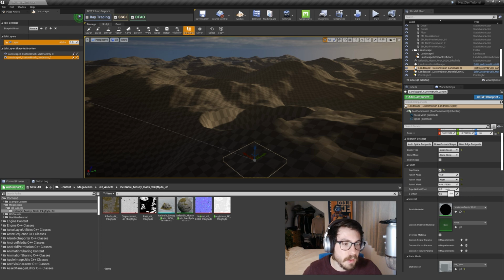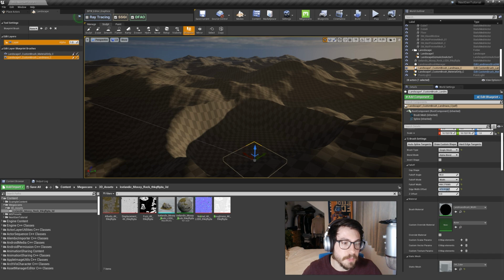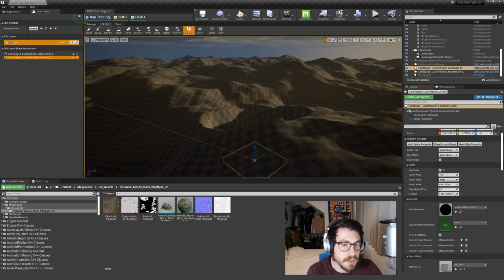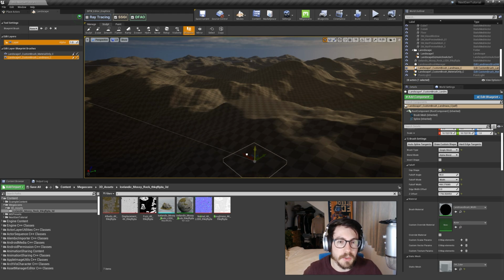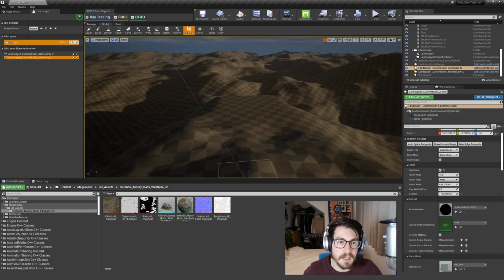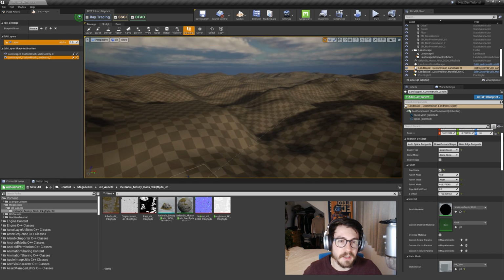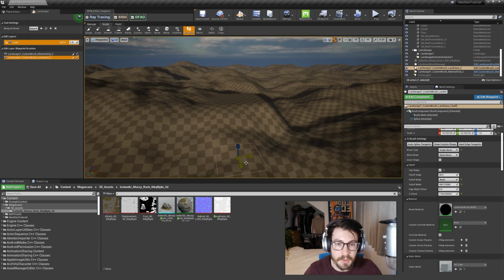And then I'm going to just increase the Z offset, so something a lot higher above the cube, basically, and by doing that I can have the cube underneath the landscape, but the affected area will be on the landscape, right?